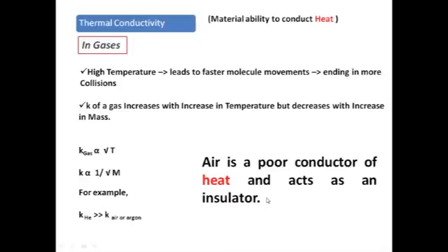In false roofing, for example, to prevent heat gain in summer or heat loss from the room to outside in winter, false roofing is the best proposal. By making a false roofing, the air is trapped between the main roof and false roof. When it is in stagnant condition, it prevents the rate of heat transfer by means of conduction, and thereby the room energy is maintained.